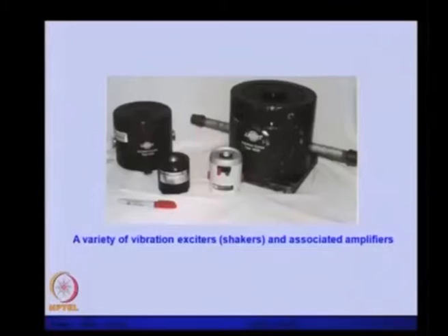With this we can excite the machinery externally, and we can choose either the frequency of excitation or its amplitude, or even the kind of excitation force we want to give, like sinusoidal, two frequency signal, multiple frequency signal, or random signal. Depending upon the application we can excite, and then measure the corresponding change in the vibration, which can be used to find the condition of the machine.